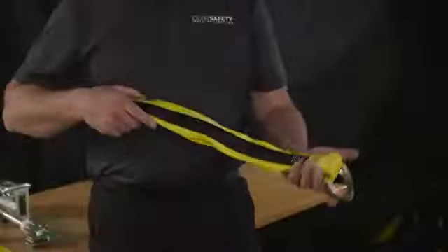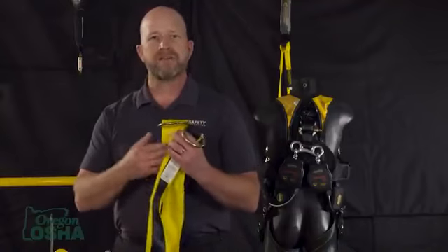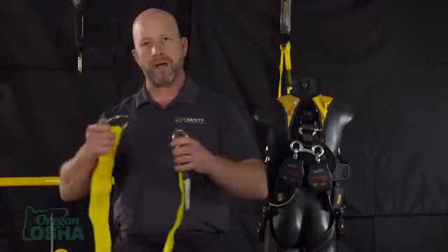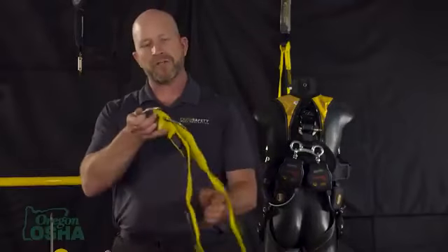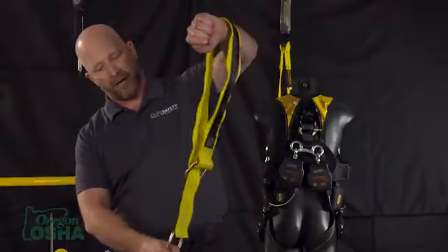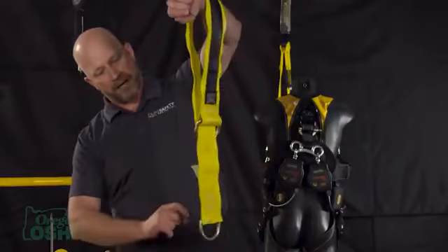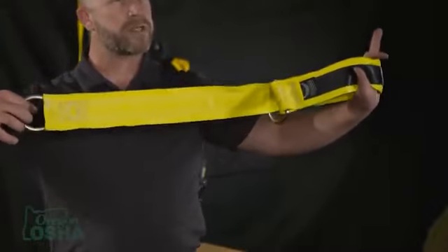The nice thing of these is that they're very easy to install. The structural part is this black part, where you can see that's where the webbing is sewn in and the D-rings are. And the yellow backer part is that of a softener. So as you're wrapping it around something that has sharp or burred edges in the construction world, you just choke it back around whatever anchor it's like that, and then you can hang your retractable from there. If you're using a horizontal lifeline, in many cases they can be used vertically this way, putting some tension in.